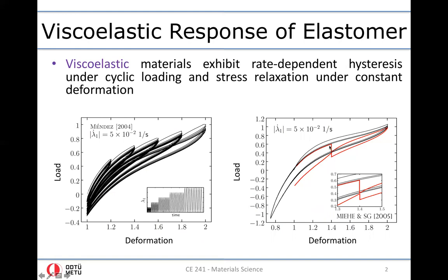And in the fourth cycle, somewhere at a strain value of about 40%, we stop the external deformation and observe what happens to the stress. As you see in this close-up, stress relaxes, in other words, reduces for the constant deformation.